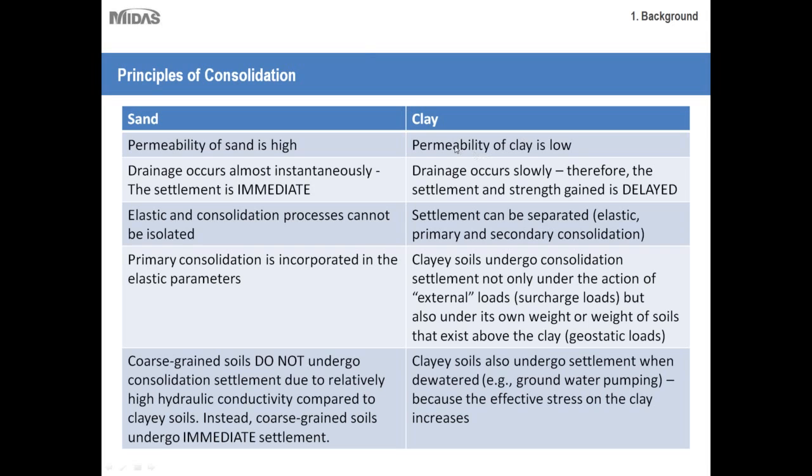Whereas if you have a large piece of clay and you were to pour water on top, the water would just sort of congeal along the top, and it would take maybe even a couple of days before that water actually seeped into the clay itself, let alone seep to the other side. Now imagine that on a much larger scale, having a large clay layer that's saturated and placing a very large structure on it. In order for that water to drain or to be pushed out of those tiny clay pores would take weeks or years.